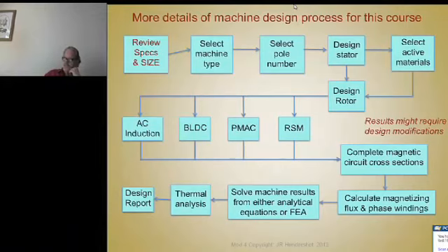For example, if magnet prices continue to escalate in cost, maybe you want to use your automotive motor for a car or a traction application as an induction machine for a few years, or a reluctance synchronous machine until the price of magnets comes back down, and then maybe you want to put the permanent magnet rotor inside that stator. Or maybe you want to offer both at two different prices and two different performance levels. That's another thing that might be worth doing.